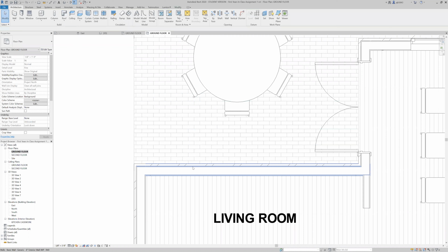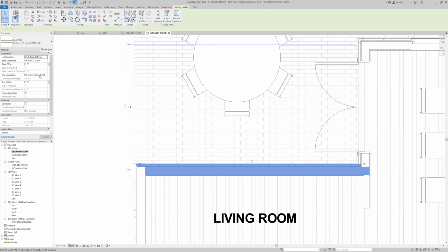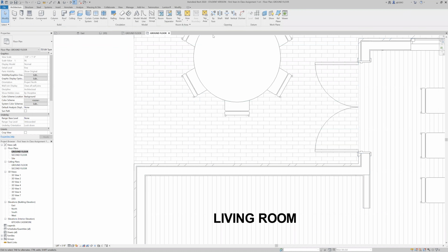The construction of this wall in this particular model is actually double height. So if we split the wall in half, then we will lose the wall on the second floor as well, and it'll also expose the floor assembly. So the best way to do this is with something I touched on earlier, which is also under the Architecture tab, and that is Wall Opening.